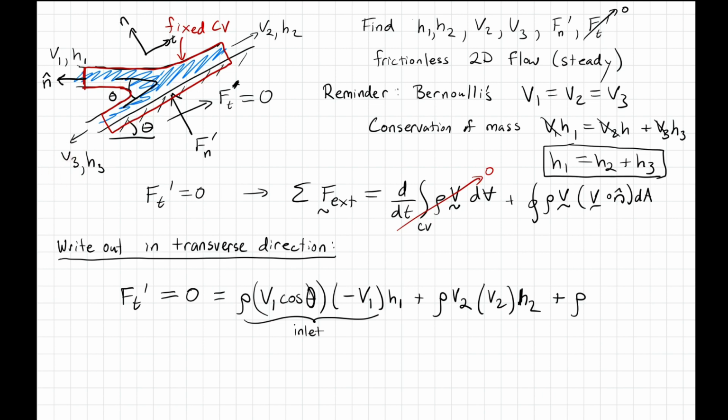So the absolute, remember, this is not an absolute value. This actually includes the directionality. So in this coordinate system, the value of the velocity would be negative v3. So that's an important thing to track down. And then the value of v dot n, so again, v goes this way and the outward normal also goes in that direction. And so v dot n is v3 times a, which is just h3.